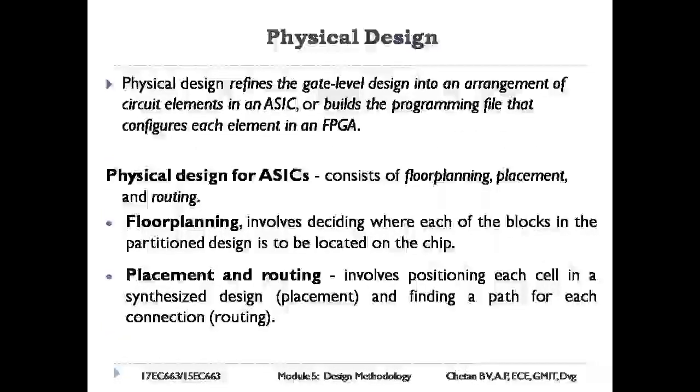Physical design. Physical design refines the gate level design into an arrangement of circuit elements in an ASIC, or builds the programming file that configures each element in an FPGA. Physical design of ASICs consists of floor planning, placement, and routing.